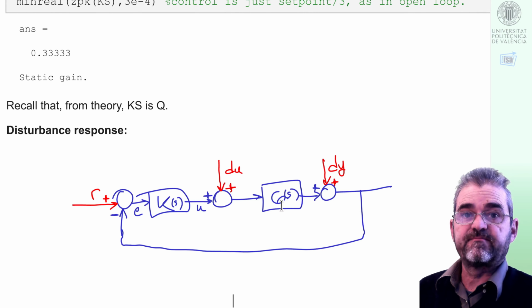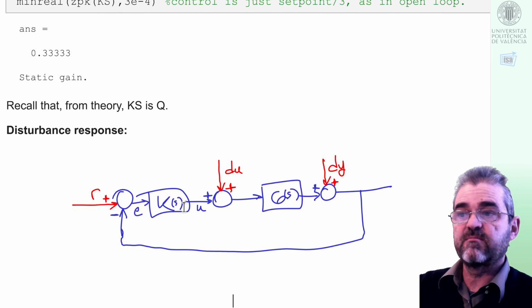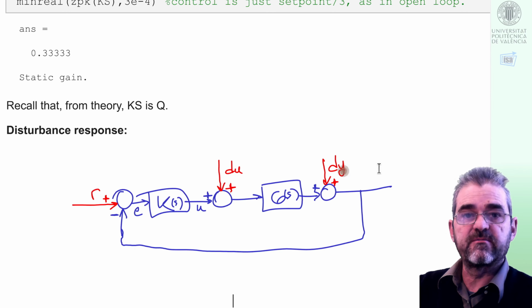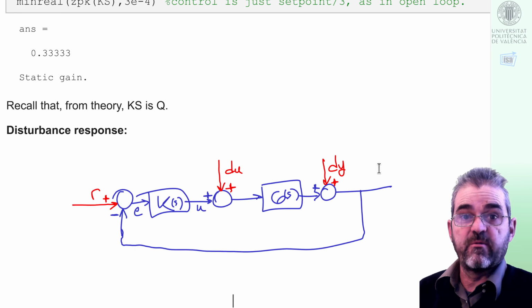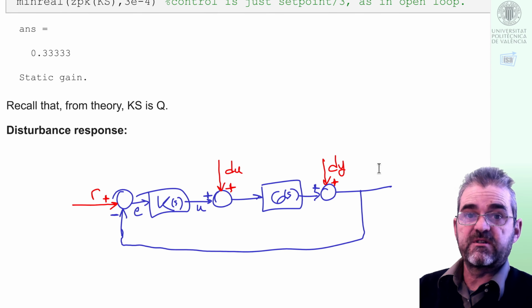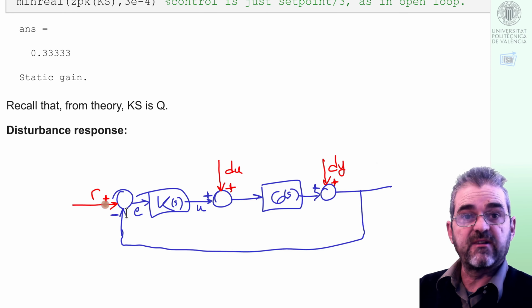We converted that to a standard regulator, which in this case had a PID form, because the plant was second order, and as it had integral action, we discovered that the settling time to all these three inputs, setpoint, input and output disturbances, was around 1.5 seconds, which we were happy with, and of course, due to the integral action of the controller, the error was 0 both in setpoint tracking and in disturbance rejection tasks.